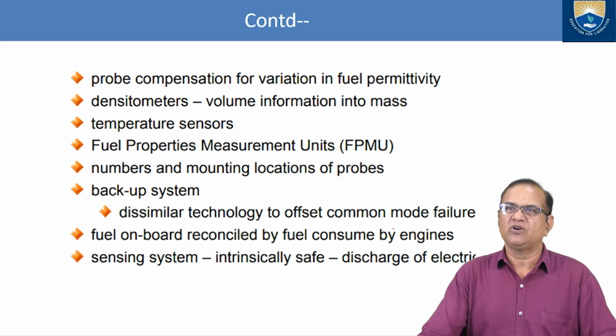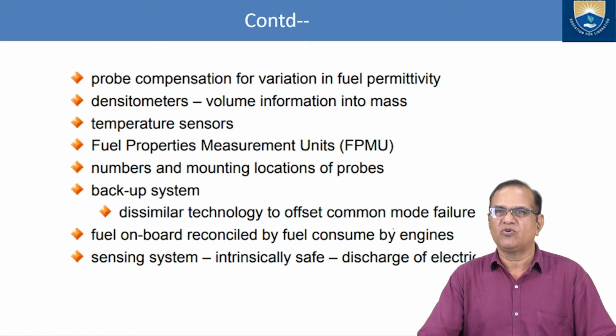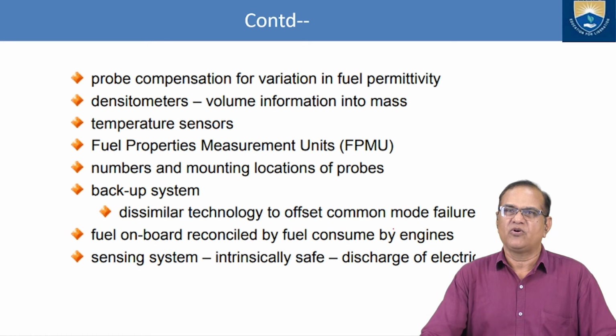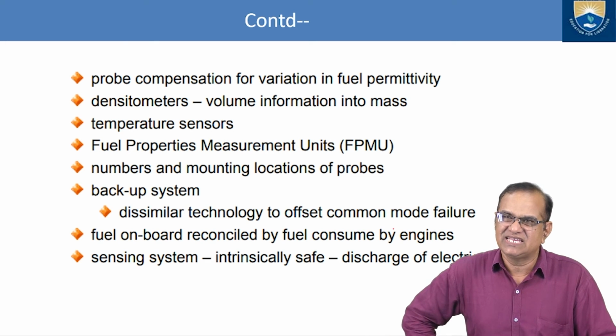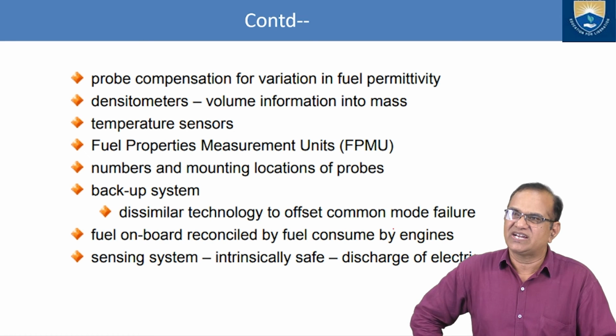Number and mounted location of the probes. Backup system: dissimilar technology to offset common mode failure. Fuel on board reconciled by fuel consumed by the engine. Sensing system, intrinsically safe, to avoid discharge of electrical energy.